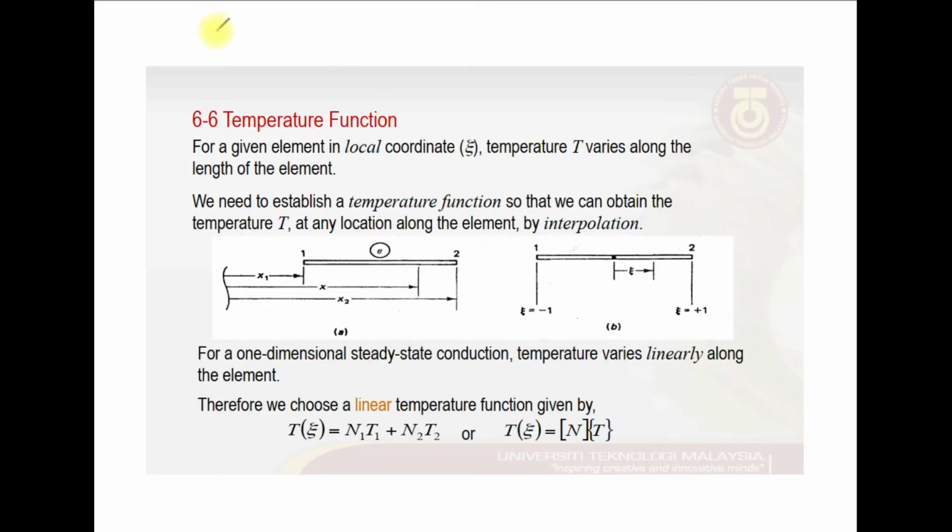If we still can remember, when we solve structural problems in finite element, we are solving the simultaneous equations in the form of kq equal to f, where k is the element stiffness matrix of our geometries or structures, f is the applied loads that are applied to our structures, and q is the desired displacements to be determined once the load is applied to the structures.